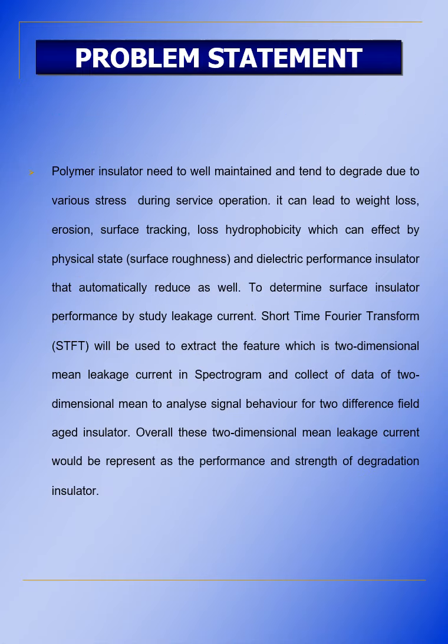For the problem statement, polymer insulator needs to be well made, and if not, it can accelerate the degradation of the insulator due to various stresses experienced by outdoor insulators. It can lead to weight loss, erosion, surface cracking, and loss of hydrophobicity, and many more. The various stresses can affect the physical state, and the dielectric performance of the insulator will be reduced as well. Besides, to determine the surface performance, we study the leakage current parameter.